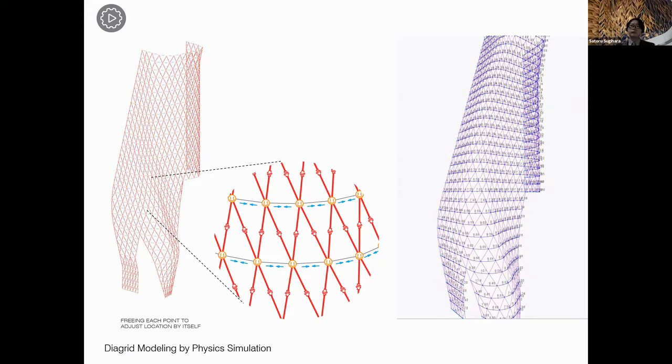The term for this technique is mesh relaxation. This one uses tension and a special force to maintain the tangency between one another. This makes the line smooth and continuous, which has a certain benefit in structural performance. If it's discontinuous or there's a kink, that's a weak point.